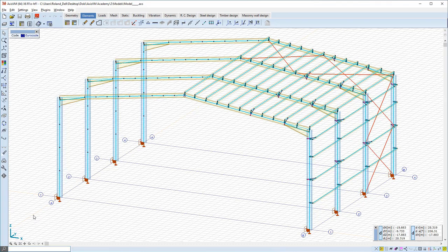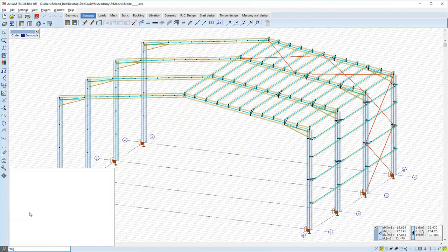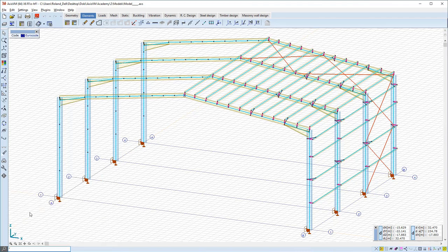So to perform the selection of entities which will be copied, a star sign is entered and first the rigid element is searched in the search bar. Since we are in multiple criteria mode, pressing Enter gives the option to add another entity, so we search for node-to-node links and press Enter again. Pressing Enter twice will perform the selection.